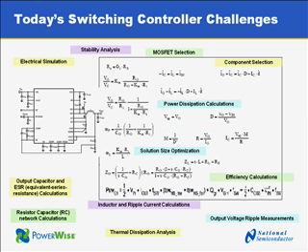To calculate a synchronous switching device, in this case a controller with external FETs that can be seen here and there, it took all these formulas that we show on this slide to calculate inductor and ripple current calculations, to do component selection, to do MOSFET selection, electrical simulation, stability analysis. All these formulas were necessary to do a good design.